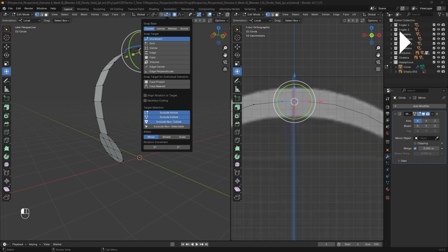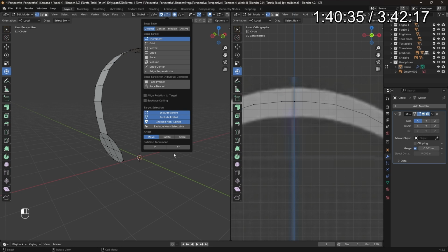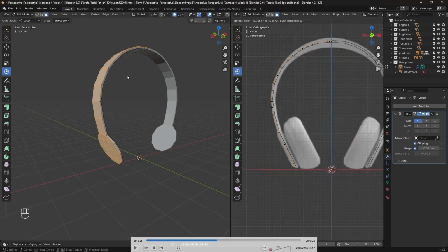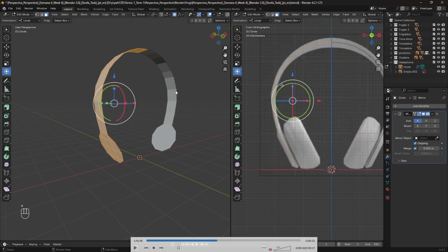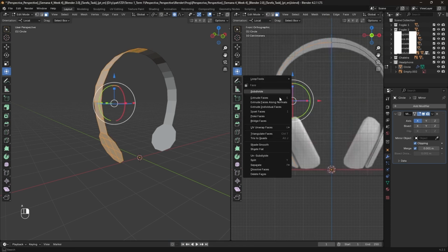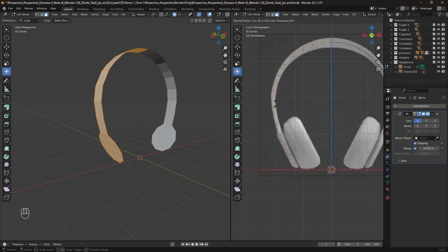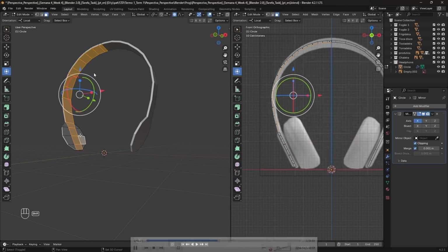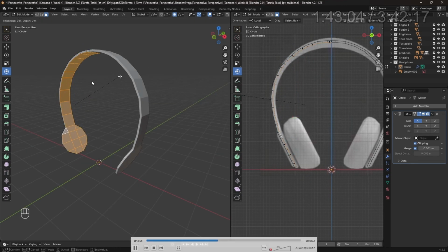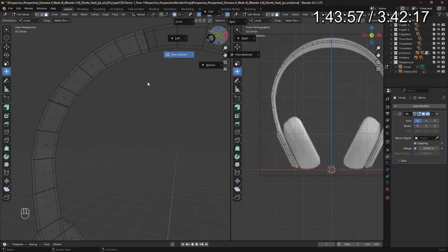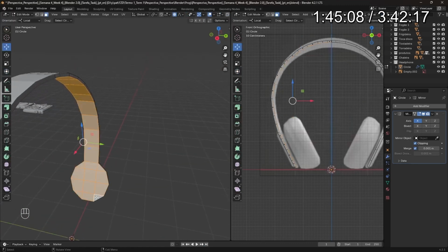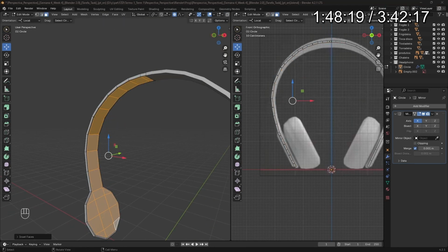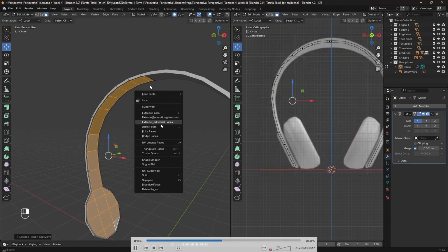Let me just hit play over here to position this accurately, but after that I decided to extrude this face. Extrude along normal. So I extruded this, and I also selected all these faces because I wanted to inset it, but I had this problem, so I needed to spend a little bit of time trying to fix it. Right here I managed to fix it.